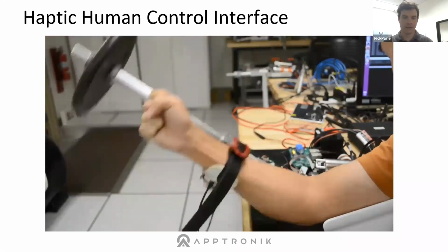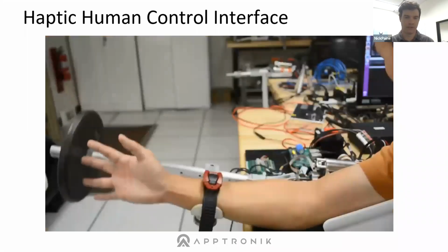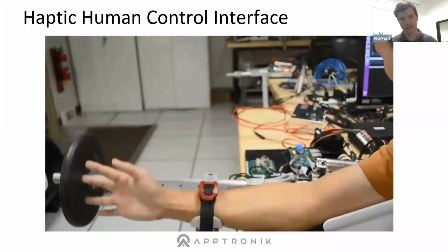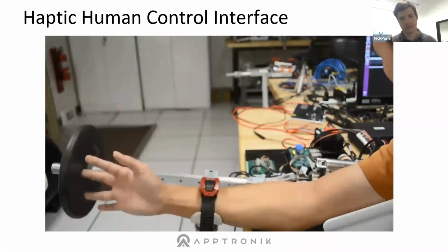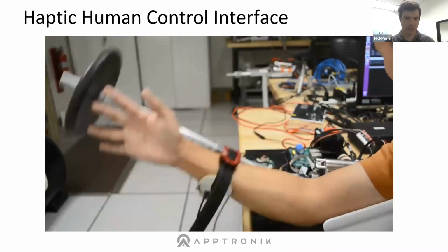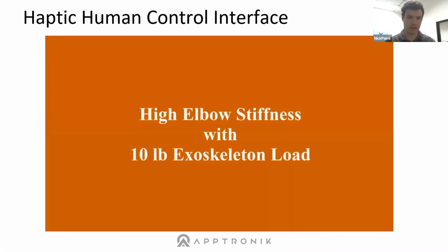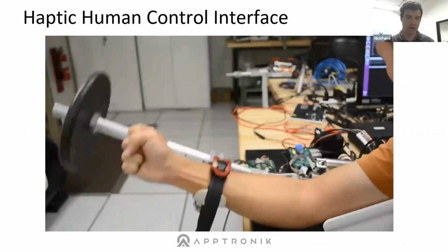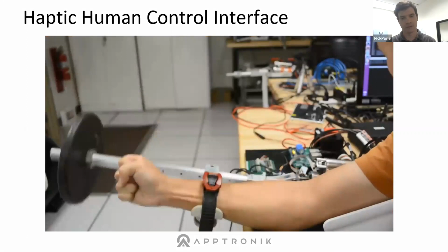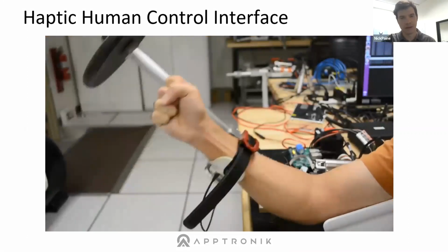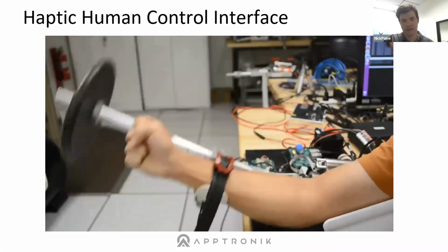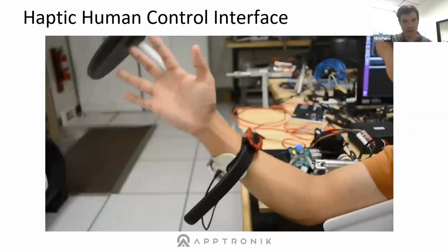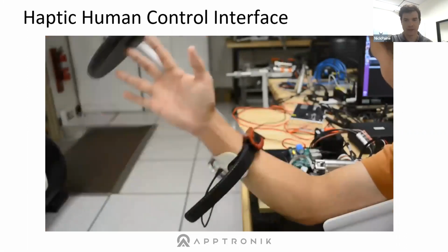The human then puts their arm into this cuff, and there's a cable coming down from that cuff that contains a force sensor, and that force sensor is measuring interaction forces between the human and the exoskeleton or the device. The haptic or feedback control then is trying to minimize this interaction force. And so that's what I mean by this kind of feedback control mentality. You can also layer on top of this a feed-forward controller, of course, by given knowledge of the mass and its location.